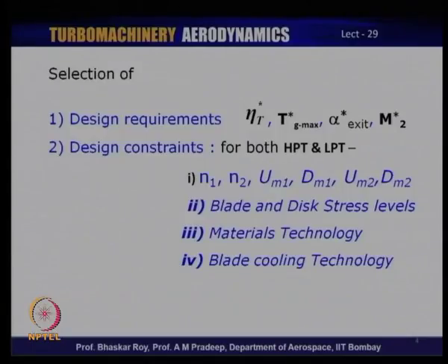And then of course, the exit flow angle. Now, exit flow angle of the turbine is important, especially if you have a nozzle as you have in aero engines. The nozzle of course helps maximize the thrust that is indeed required for flying of the aircraft. Now, in the process of creation of thrust, what you require is a straight jet, which means exit flow angle from the turbine should be 0. The flow should go out straight and go straight into the nozzle and go out straight axially. That is when you have the maximization of your thrust creation.